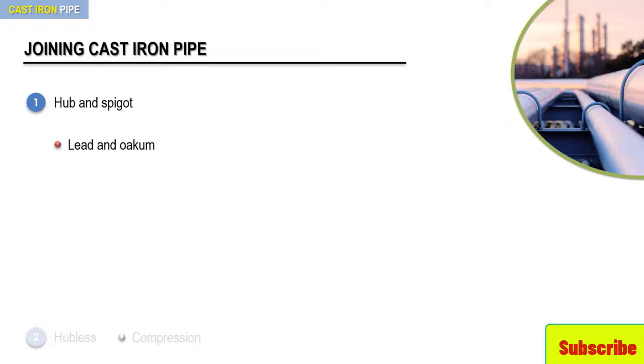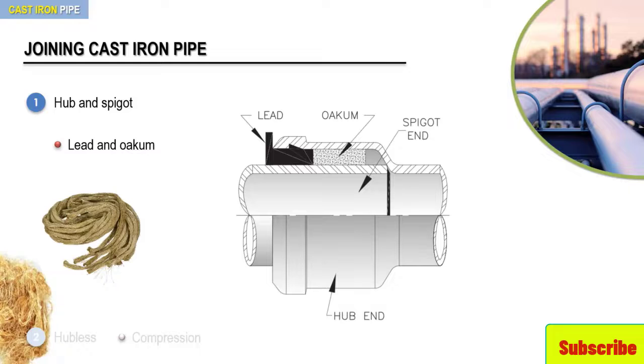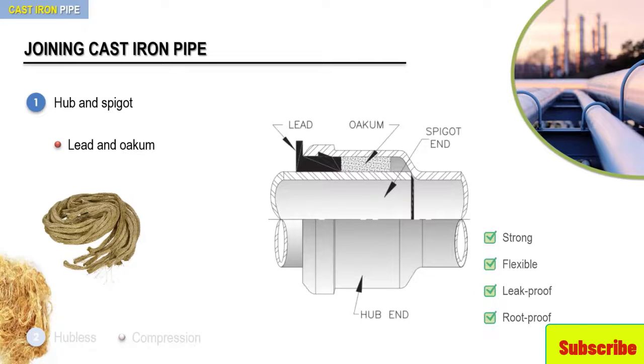The lead and oakum joint, as in this example, is made with oakum fiber and molten lead to create a strong, flexible, leak-proof, and root-proof joint. When the molten lead is poured over the waterproof oakum fiber, which is a loose packing material, the joint becomes completely sealed. Water will not leak out, and when used underground, roots cannot grow through the joints. To better illustrate how this special sealing method is used, let's have a look at the following demonstration.